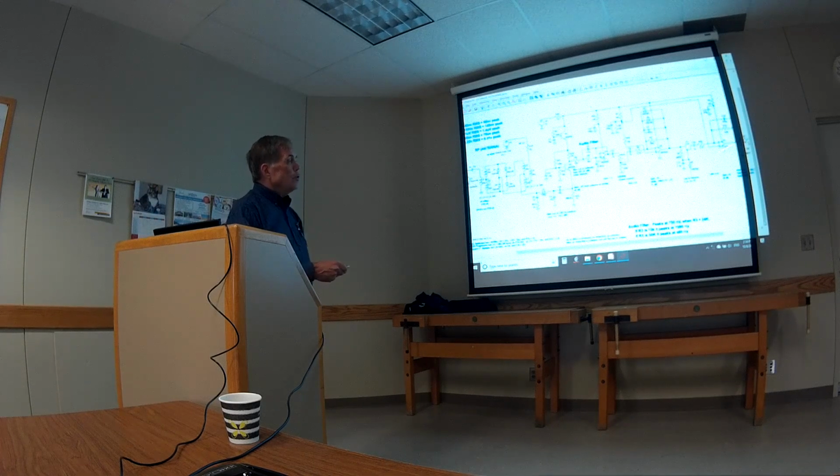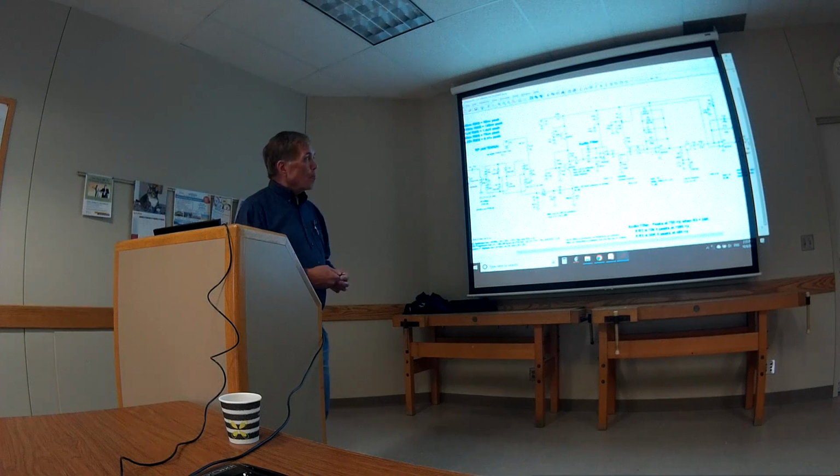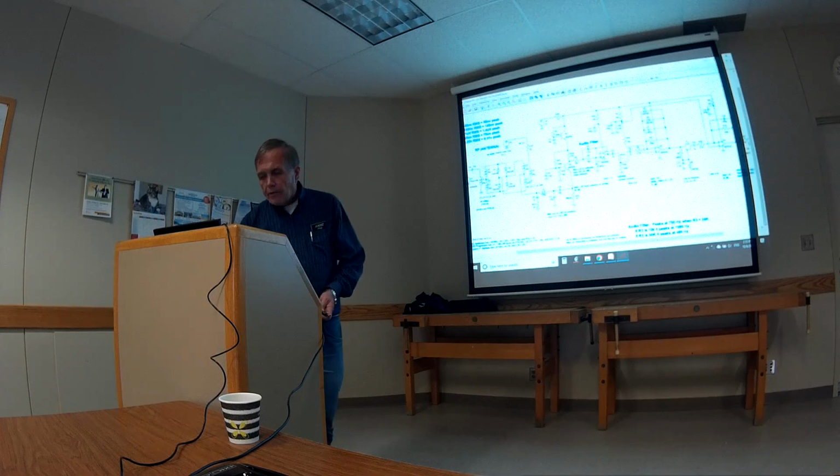And then it just has two little audio amplifiers out here. I happen to use NE5532, a very commonly used low noise amplifier, and set up with a gain of, well, 100 over 2.7K, which is about 37, a gain of 37, which is 31 dB. The thing I want to show you here is I did this whole model of that receiver that I built. There's one more amplifier out here before the speaker.